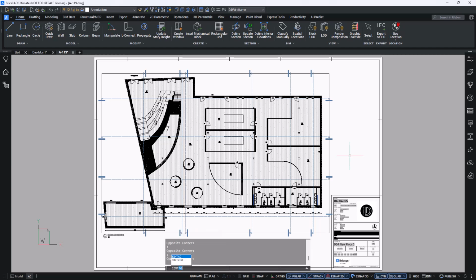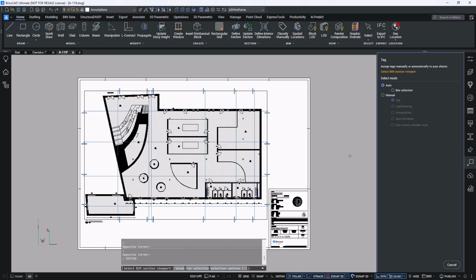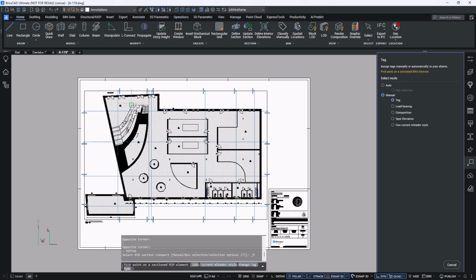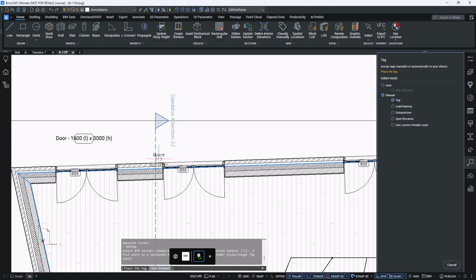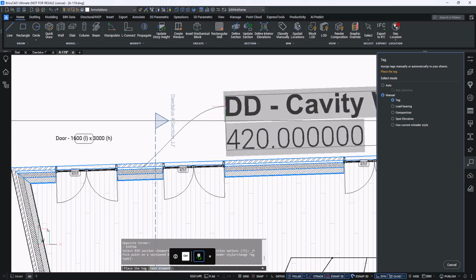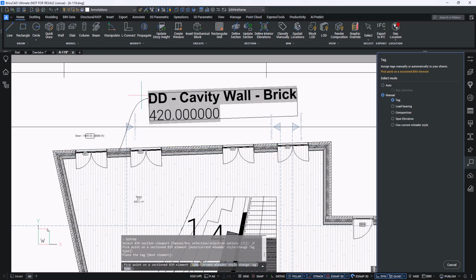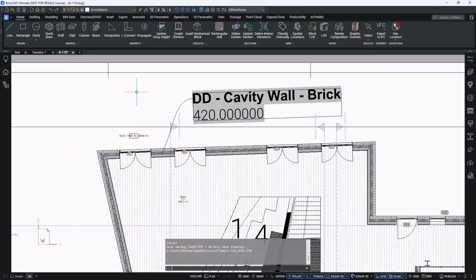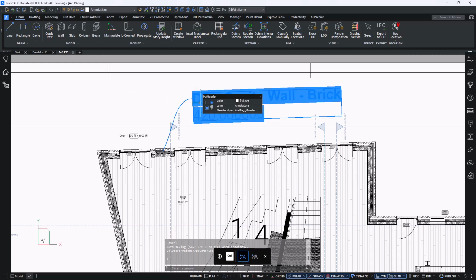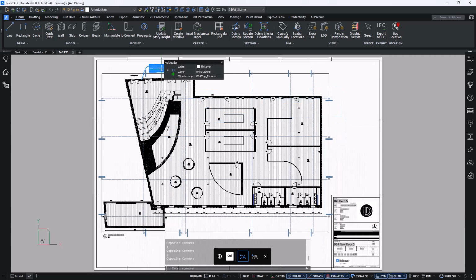When you execute the BIMTAG command, BricsCAD checks whether the source data already exists in the BIM section drawing. If not, the source data is copied from the section tag drawing file. Therefore, editing tag blocks and multi-leader styles directly in the template drawing will only affect the creation of new BIM tags. Observe that the newly created multi-leader style was used for the tag creation.